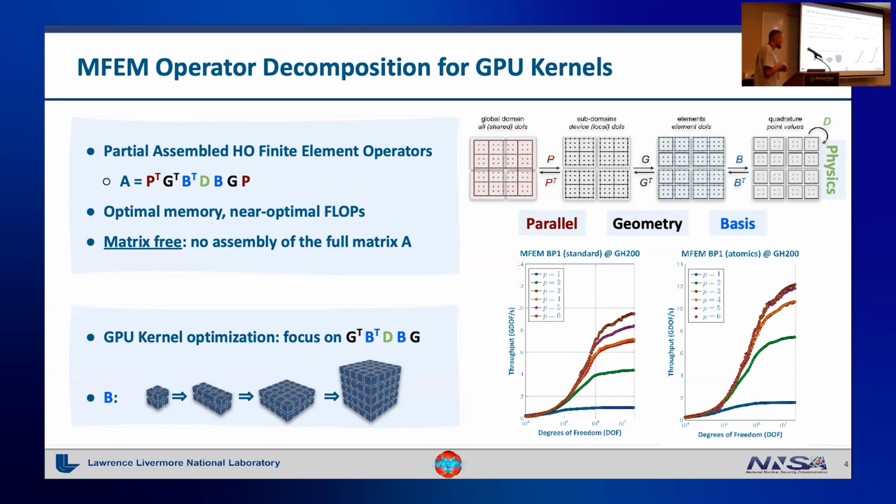An important ingredient is the Bs. These finite element bases can be just for evaluating some degrees of freedom down to the quadrature points, and usually come in different flavors. But we're using some factorization, which is a series of tensor contractions, which can be visualized pretty much like this, where you start with a 2D cube tensor, and you apply dimension by dimension x, y, and z to end up at quadrature points with a 5 cube quad point tensor there.